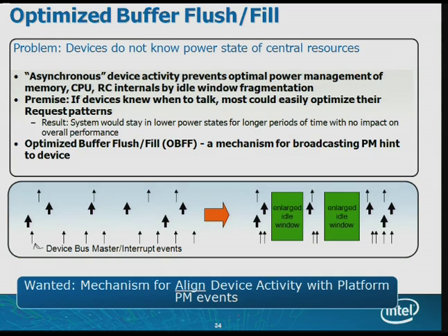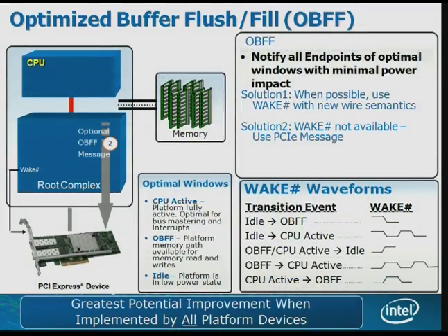So the idea with this one is to provide information from the system to the device on what state the system is in, so that the device could say, well, let me not bother the system now, let me try to coalesce as many practical requests over some time, and then create, in essence, rather than spreading the traffic, windows of opportunity where we can exploit the power management opportunity. And that is done using either a sideband signal called WAKE or using in-band messaging constructs.